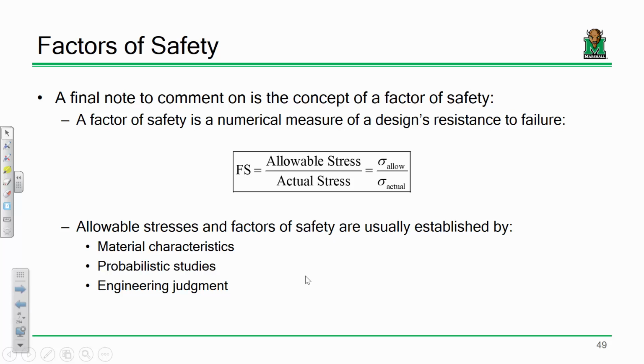So there's one there. Another important point on factors of safety, which isn't really mentioned here, is specifications. Some specifications will actually dictate to you this is the factor of safety that you shall employ when you're designing this type of system, and that's very common as well. There's also the idea of uncertainty and how we characterize that in engineering, but a lot of it boils down to engineering judgment. In short, the more uncertain you are about a scenario, the higher your factor of safety should be. What that factor of safety should be in what scenario, it depends.